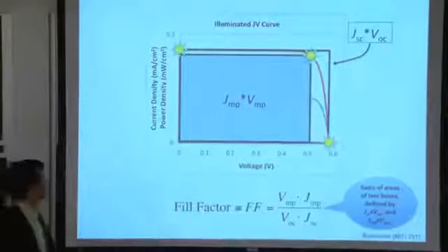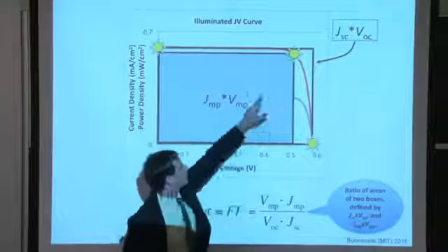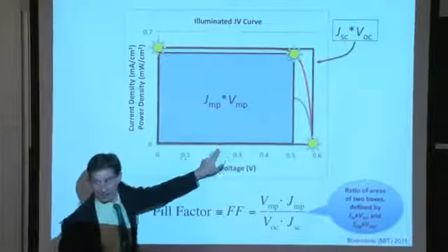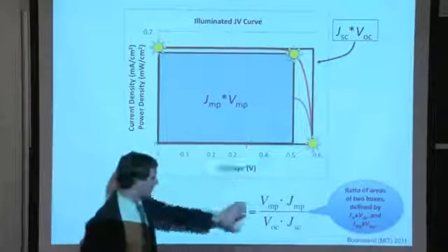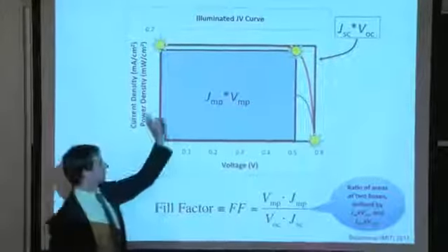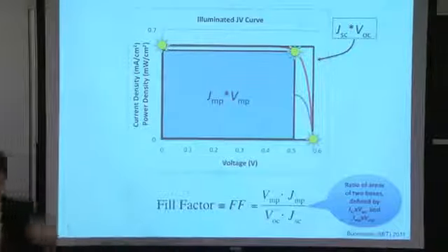If your fill factor is very poor, that means that that sun right over there that denotes the maximum power point is being dragged toward the origin. That means that the area of this blue box is growing smaller relative to the area of this clear box. The fill factor is going down. That means you're filling less of this maximum square box function defined by VOC-JSC.